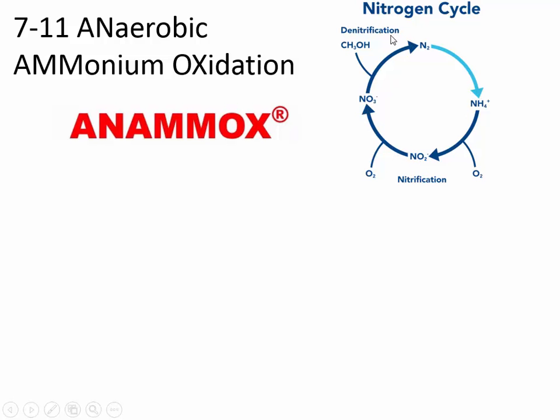And then it was in the anaerobic reactor that denitrification occurred, taking nitrate to nitrogen gas. So this is just a really good summary of the nitrogen cycle that we were talking about last week. You notice it's indicating that sometimes you have to add methanol as a carbon source during denitrification. So that's the traditional route.